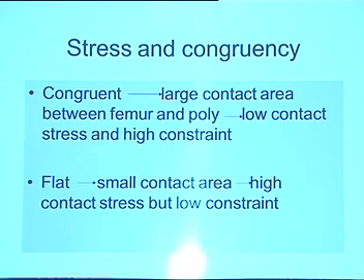Stress and congruency, these are two important things. Congruent means a large contact area between the femur and poly, low contact stress and high constraint. But a flat surface has a small contact area, high contact stress but low constraint. So these are two ways of looking at it.